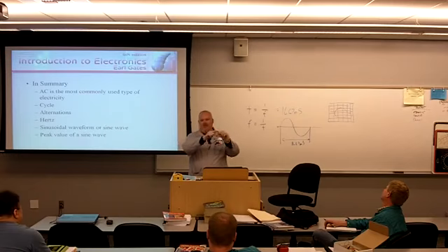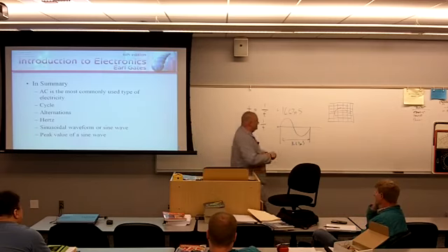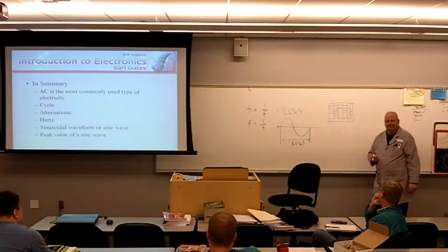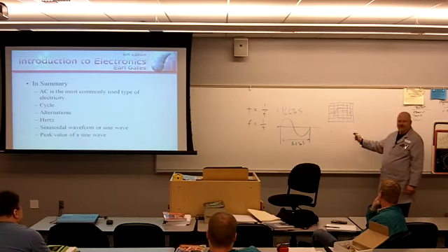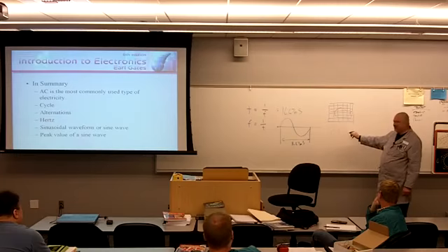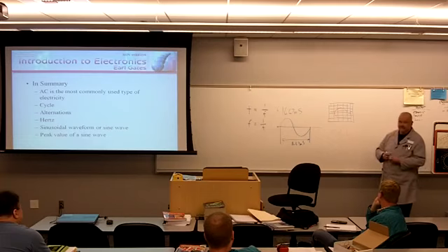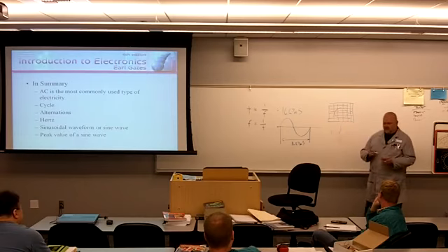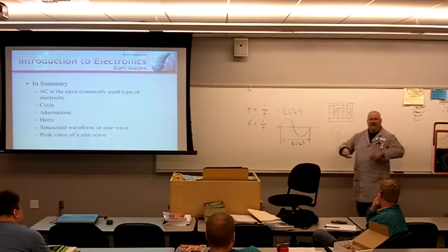Because the unknown on my vertical axis matches the known on my horizontal axis in a mix. And if I got something that looked like this, it's a harmonic. If I'm at the perfect frequency, it's going to be a circle. If I'm at double that frequency, it's going to give me one of these things. So I could get all these different patterns on the oscilloscope.